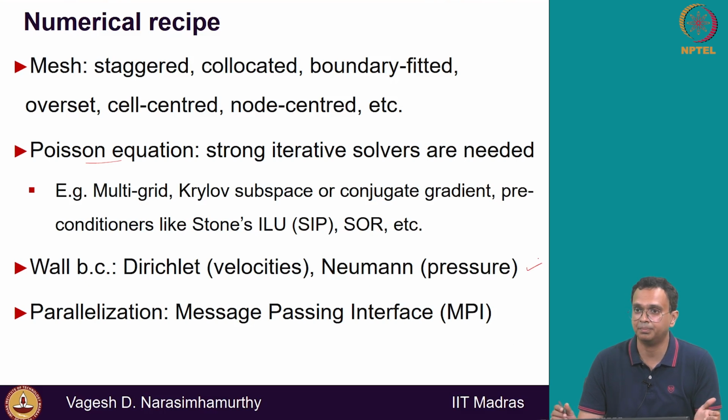And since the mesh size is very large, okay, typically goes into tens or hundreds of millions or even a billion. If the mesh size is so large, you would need lots of memory, right? Probably several hundred GBs or even a terabyte of memory is required. So with that kind of memory requirement, a single computer cannot do this, right? The memory on a single computer typically goes like maybe maximum 100 GB or so. You would need like terabytes of RAM memory.